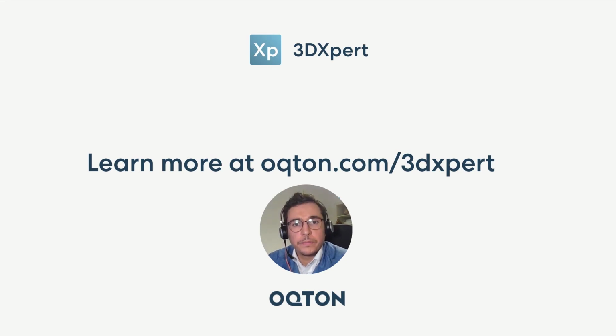And that's already it. The super easy workflow in 3DXpert in combination with Trumpf Sprint, where you can just continue working with your solid file, do all the work in 3DXpert, have still the material parameters management and slicing done by Trumpf Sprint, but you still just click on slicing in 3DXpert and export the WZA file and put it on your machine.